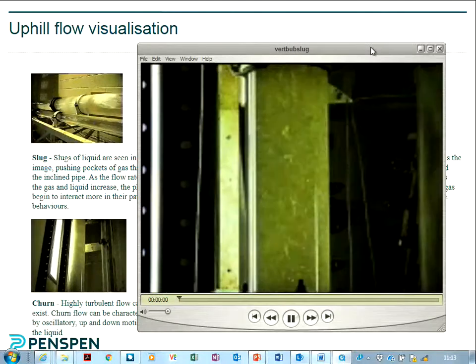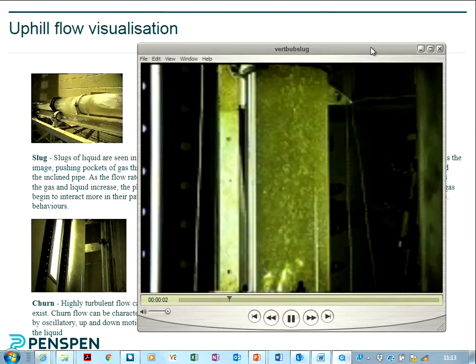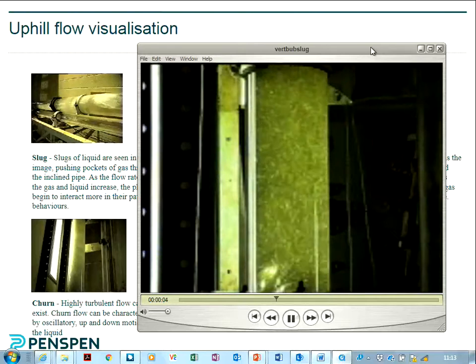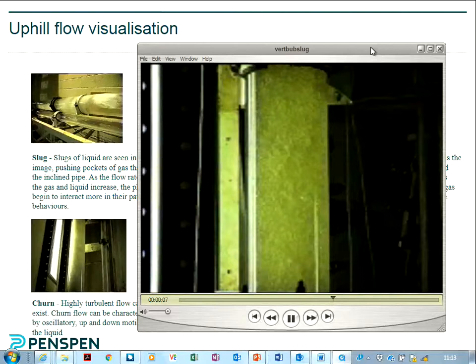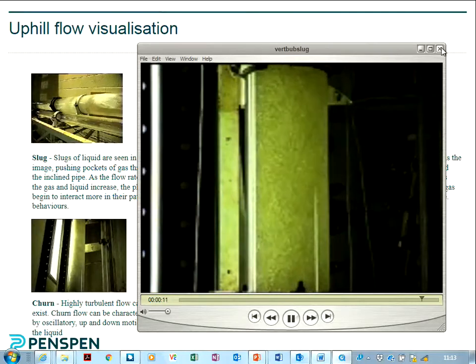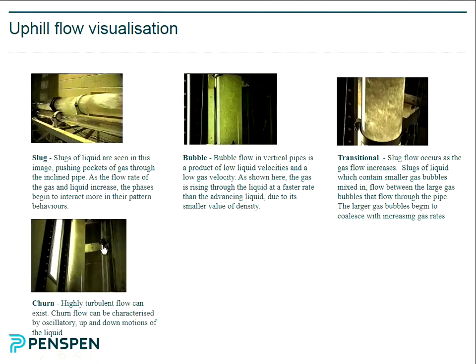These are examples of vertical flow maps. They have very much different parameters. You'll find different researchers, there's a lot of different schools of thought with multi-phase flow. Lots of different researchers, they're normally named after people. This has got bubble flow, froth flow, plug flow, slug flow, mist flow, for small amounts of gas, for large amounts of gas, small amount of liquid, basically.